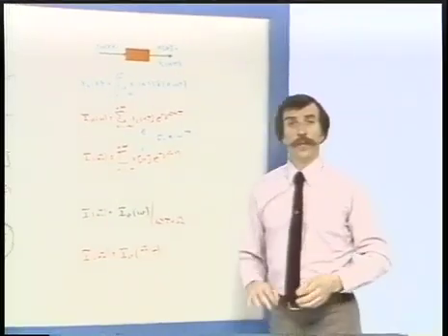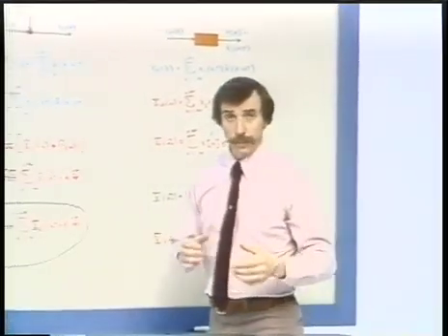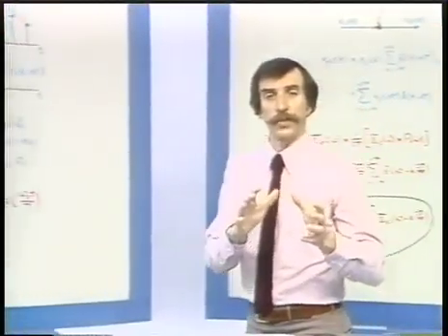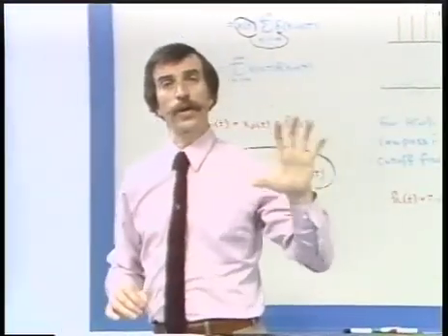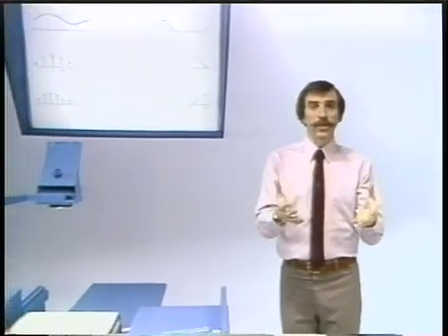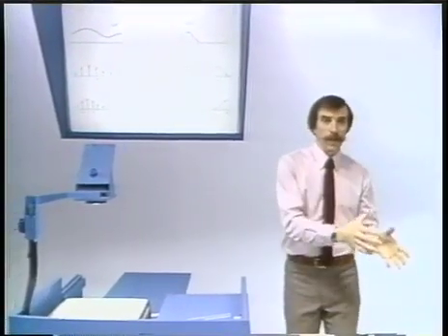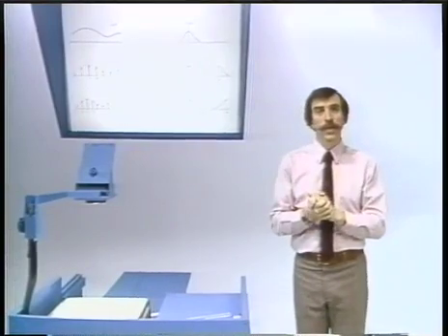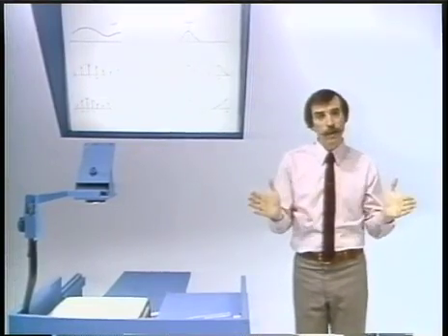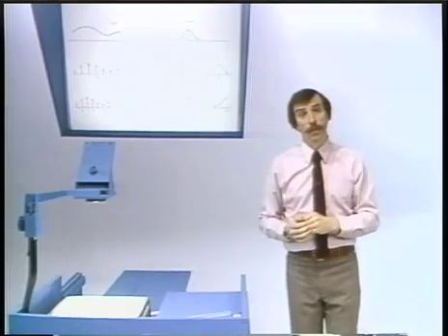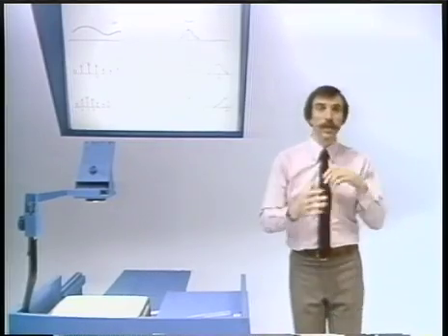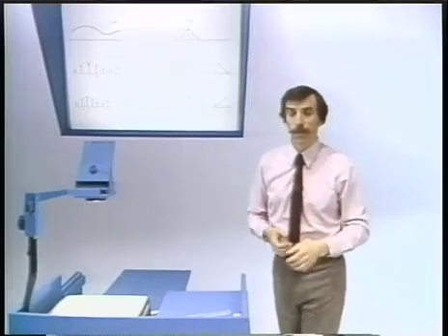All right, so we have then this two-step process. The first step is taking the continuous time signal, sampling it with an impulse train. In the frequency domain, that corresponds to replicating the Fourier transform of the original continuous time signal. The second step is relabeling that, in effect turning it into a sequence, and what that does in the frequency domain is provide us with a rescaling of the frequency axis, or as we'll see, a frequency normalization which is associated with a corresponding time normalization in the time domain.